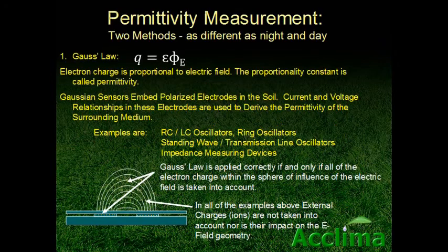Nearly all soil water content measuring devices are based on the measurement of the dielectric constant, or permittivity of the soil, which is dominated by water content. By measuring permittivity accurately, it's then possible to come up with an accurate measurement of water content through the Topp equation, or a dielectric mixing model. Permittivity manifests itself in two distinctly different but observable principles.